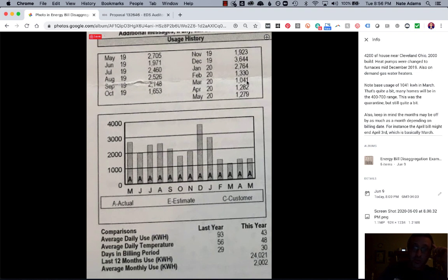Because you can find all sorts of stuff. I had one all-electric client complaining about electric bills, and there was 500 kilowatt hours that I couldn't figure out what it was just from doing this quick aggregation that I'm showing you. And yeah, it was grow lights. Life is interesting. You can find all kinds of stuff through bill disaggregation. That one still makes me chuckle quite a bit.